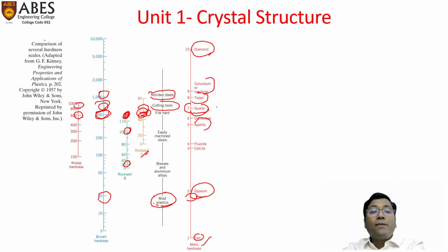So always we have to write HB something, hardness Vickers, or hardness Brinell, or hardness Knoop. We have to mention the hardness scale, or hardness Rockwell C, HRC, or HRB, hardness Rockwell B, and then that value, to properly mention the hardness value of the material.